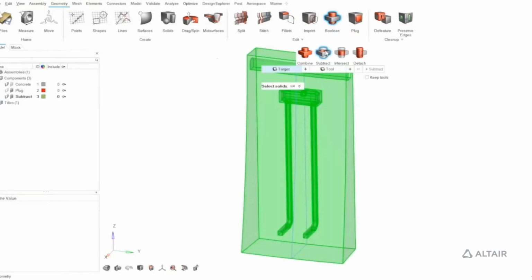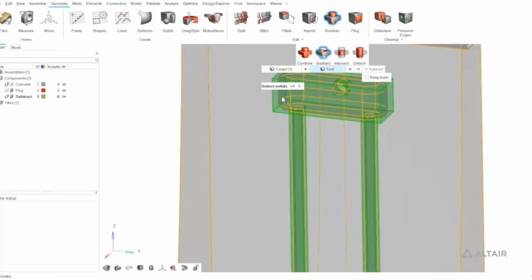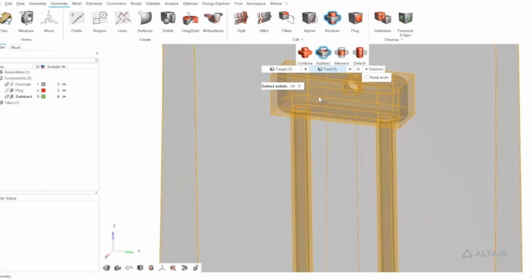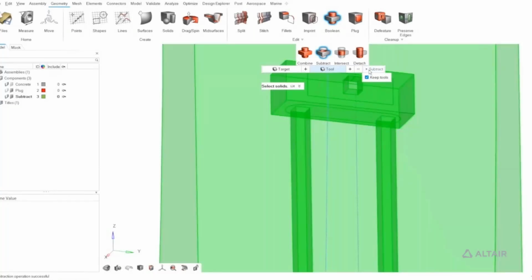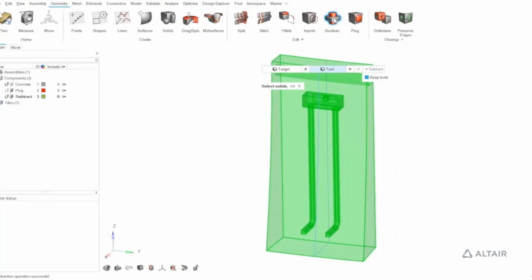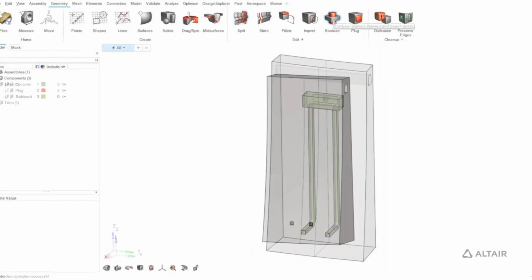Now, we can proceed with a Boolean operation to simplify the original CAD by subtracting the new simplified hole from the original. The new object that we created is bigger than the original, as we can see, but we still have the same dam. But only this time inside, the same tubes are now simplified. And this is known as a simplification process.